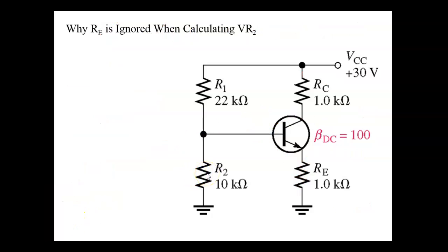Okay. So we have this sitting at what? 9.4. That gives us what? 8.7 right here. Then we got IC would be equal to 8.7 milliamps. But that's not what we're looking at. So we're going to assume a beta of 100.